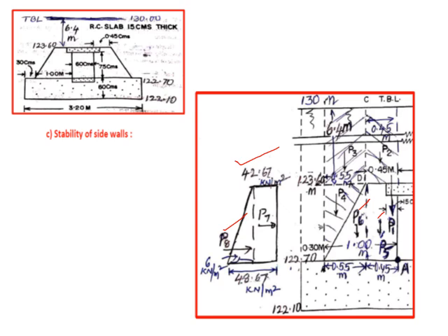P4, half into 0.55 into height 0.9 into 20, like that. So then what is P5? It is concrete. So 0.45 into 0.9 into 1 multiply by 24, because it is concrete. Here half into 0.5 into 0.9 into 1 into 24, multiplied by 24, so that gives P6. So like this we are able to calculate it.